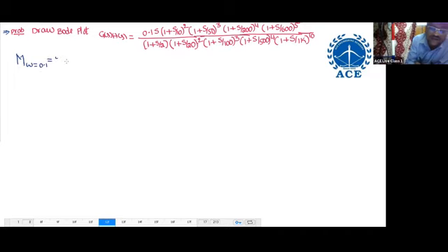That equals 20 log 0.1 plus 20 log S, which means omega, 20 log omega. Now omega is 0.1, so 20 log 0.1 plus 20 log 0.1, that is 40 log 0.1. How much will you get? Minus 40 dB. Now draw the plot.